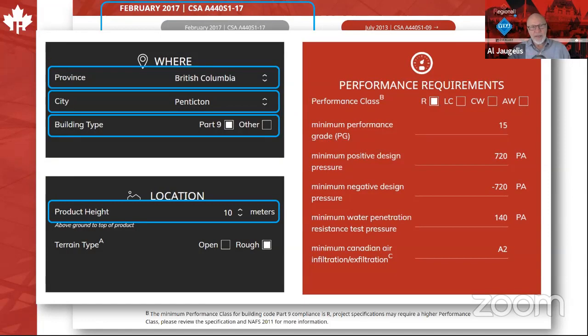And if you base your glass design and your reinforcing of the products on that highest load, you might be paying money that you don't need to reinforce everything in the building, when some of these measures might only be needed in the upper stories. So it's just worth appreciating that this evaluation does take into account the height of the fenestration product.